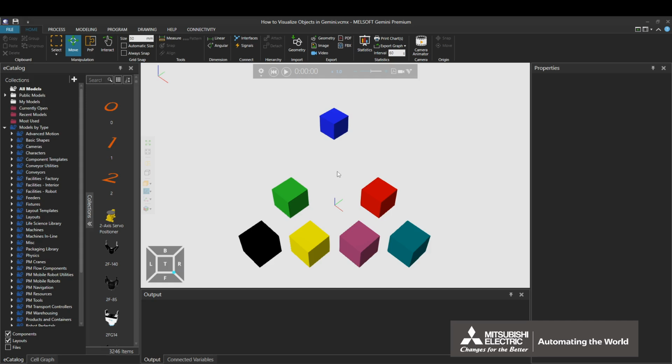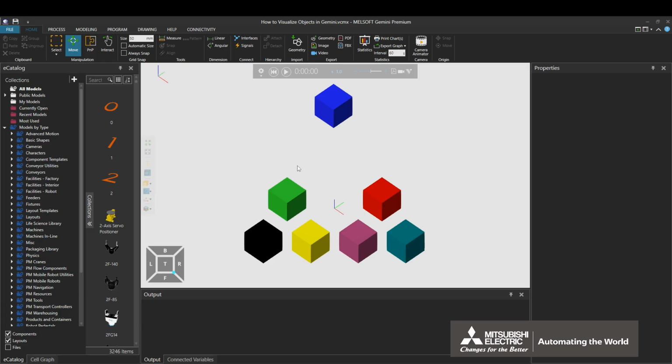Click Orthographic on the 3D World toolbar. Now, the previously moved block appears the same size as the other blocks. The Render Mode function affects how components are visualized on the 3D world, such as component lines, material surfaces, and edges. Press the Ctrl key and the N key to delete the current layout.